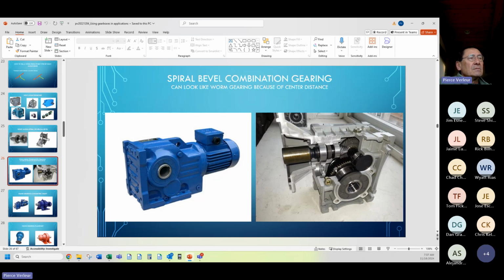Often in this set, the second set, called the second reduction, is going to be helical as opposed to straight tooth. Now, this first reduction runs obviously at motor speed here, and then this shaft is reduced. This shaft drives this shaft through the second set of gearing, further multiplying the torque and reducing the velocity.